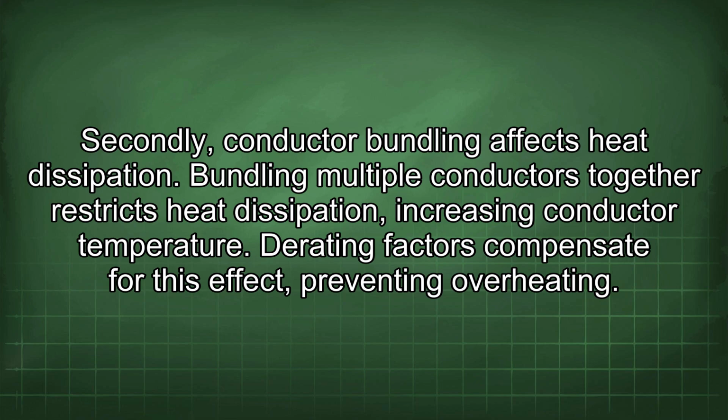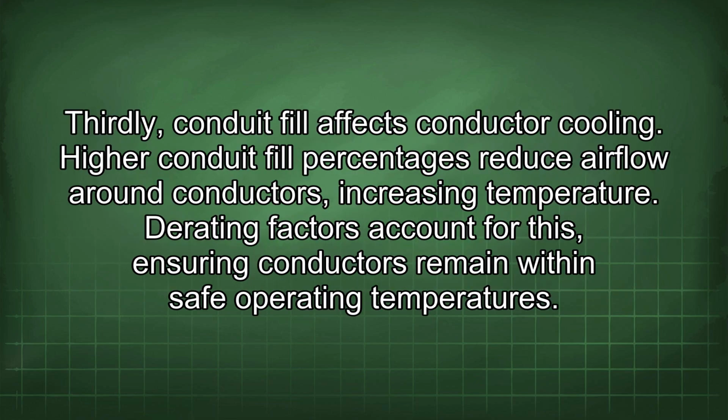Secondly, conductor bundling affects heat dissipation. Bundling multiple conductors together restricts heat dissipation, increasing conductor temperature. Derating factors compensate for this effect, preventing overheating. Thirdly, conduit fill affects conductor cooling. Higher conduit fill percentages reduce airflow around conductors, increasing temperature. Derating factors account for this, ensuring conductors remain within safe operating temperatures.